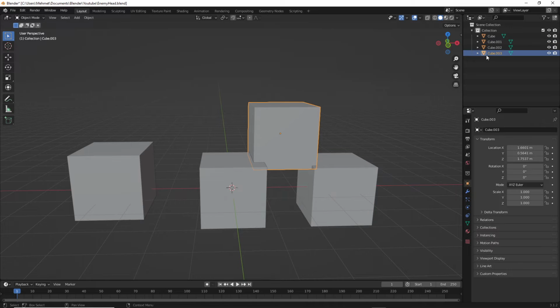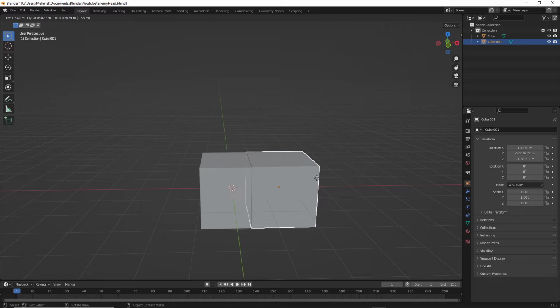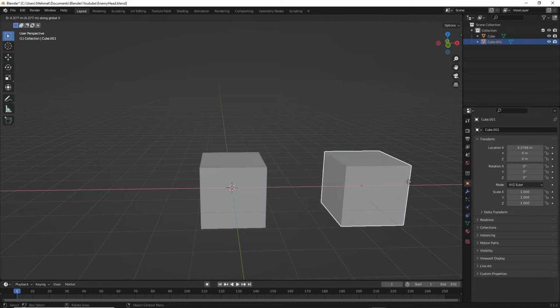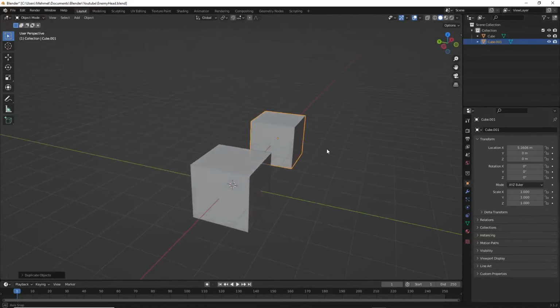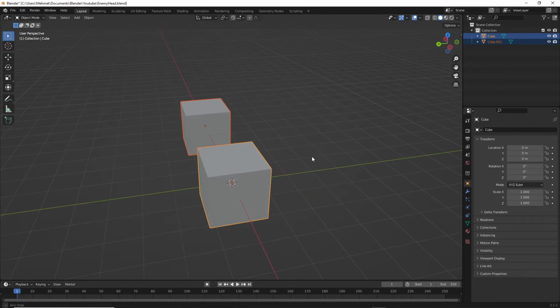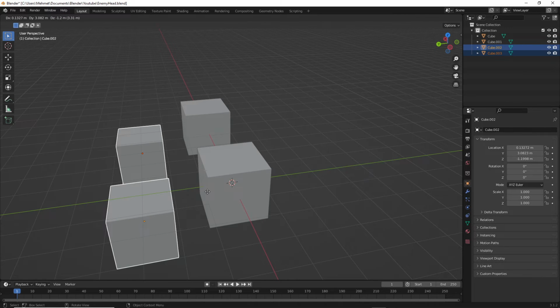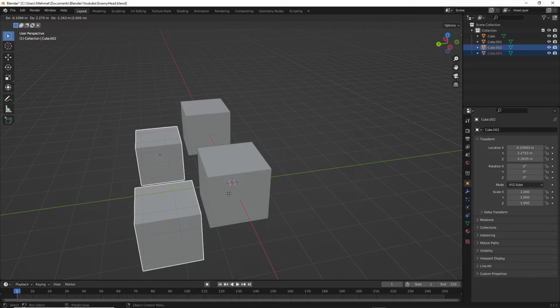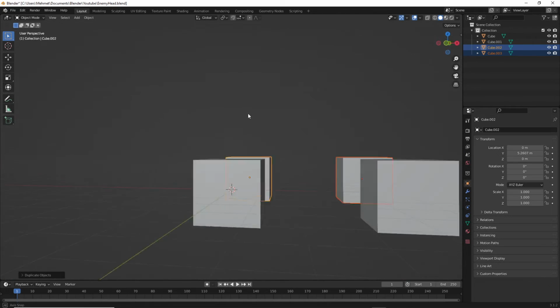Let's delete them again. Because I think it's better when you Shift D now, but then you press X, so I can move this along the axis so they are on the same height and on the same side. That's much, much, much better. And now what we can do is select this one too. And now Shift D. And this time I want to move it along this axis, so I press Y this time. And yes, something like that. Yeah, we have here 4 chair feet.